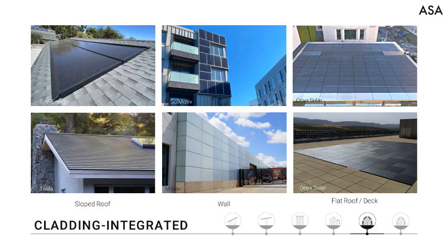PV integrated wall cladding is now being offered by various manufacturers with various surface treatments that reduce solar production, with the benefit of customizing aesthetics and concealing the solar technology from view. One challenge with these systems is identifying compatible mounting solutions. As with site integrated solar floors, similar products can be integrated into a rooftop deck or balcony with the same methodologies utilized for pedestal mounted pavers or deck tiles. In such an application, textured glass is typically utilized to form a non-slip surface.